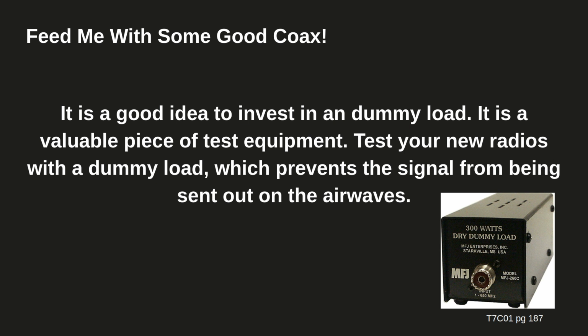And I didn't bring that one in here either. It is a good idea to invest in a dummy load. We do have one of those as well, but that's okay. It's like what's in the picture. It is a valuable piece of test equipment. Test your new radios with a dummy load, which prevents the signal from being sent out in the airwaves. And now we're going to go back to Donald.